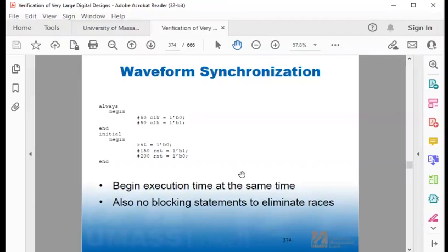So in verification, you'd probably start the reset high, then see what happened on a low going pulse and a high going pulse, because sometimes you can get some weird behavior there. So make sure that you not only go from reset to not reset, but also not reset to reset, right? In the middle of the system. So even if you have to toggle reset a couple times at the start.